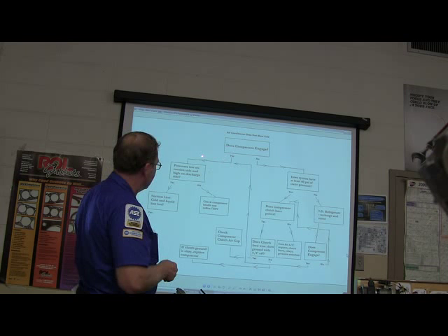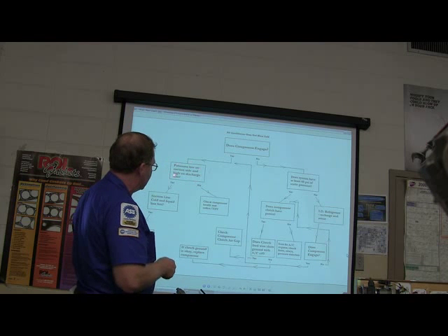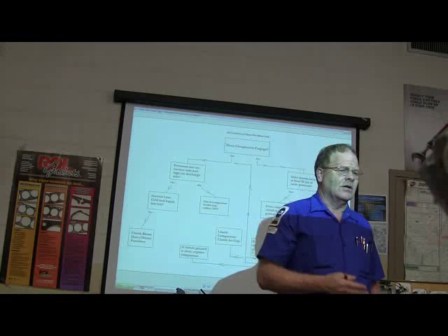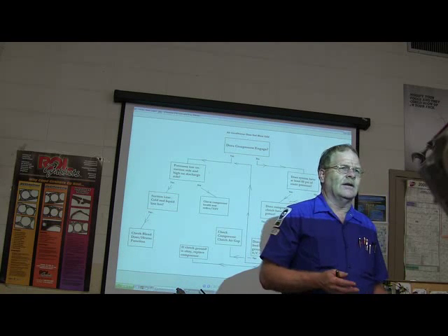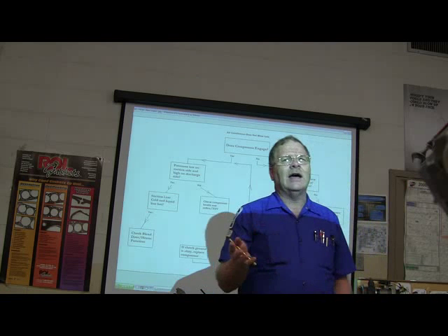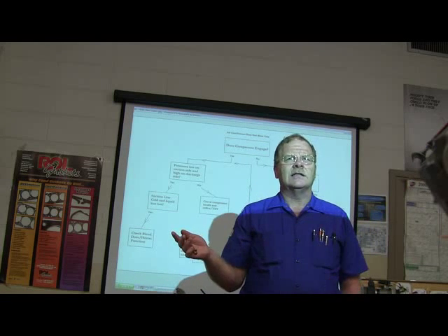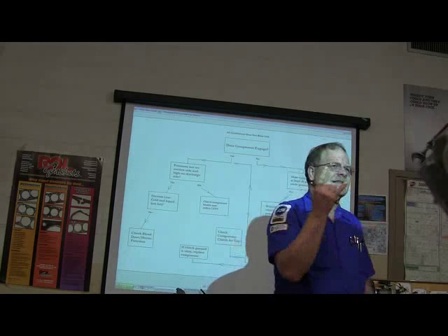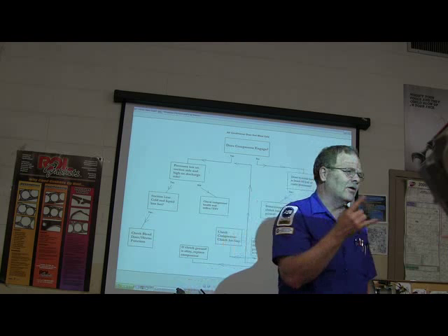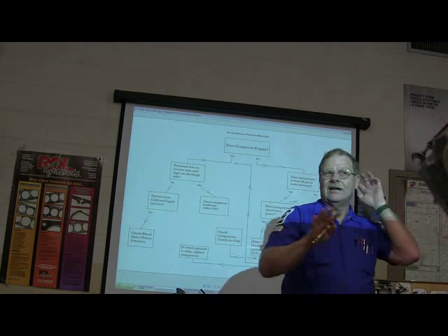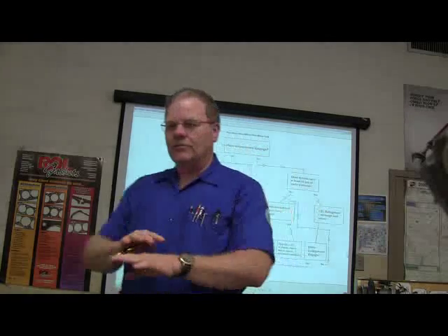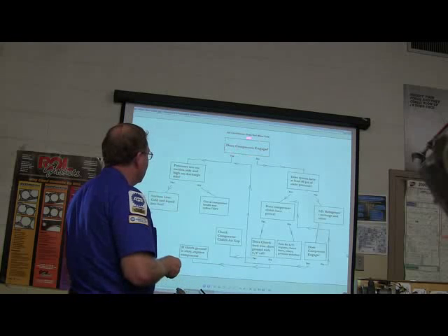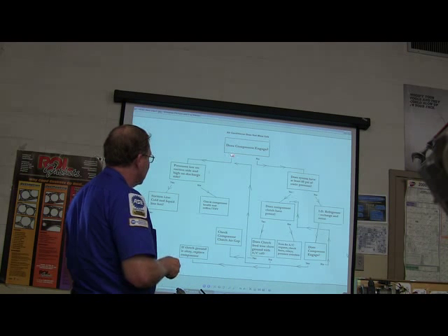If the compressor engages, are the pressures low on the suction side and high on the discharge side? Now, connecting your gauges, you're going to see some static pressure if there's refrigerant in there. And the static pressure numbers are not published anywhere. They may be between 60 and 110 pounds on each side. They're going to be pretty well equal on both sides if you haven't been running the AC. Now that's just with the gauges hooked up and the car sitting there.